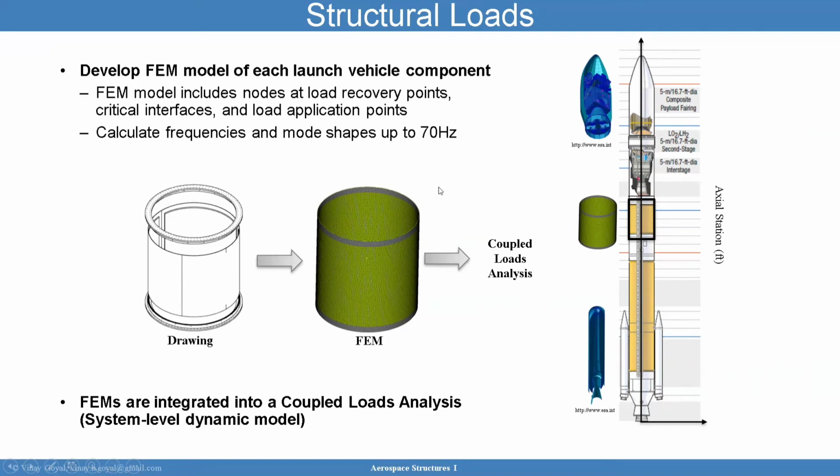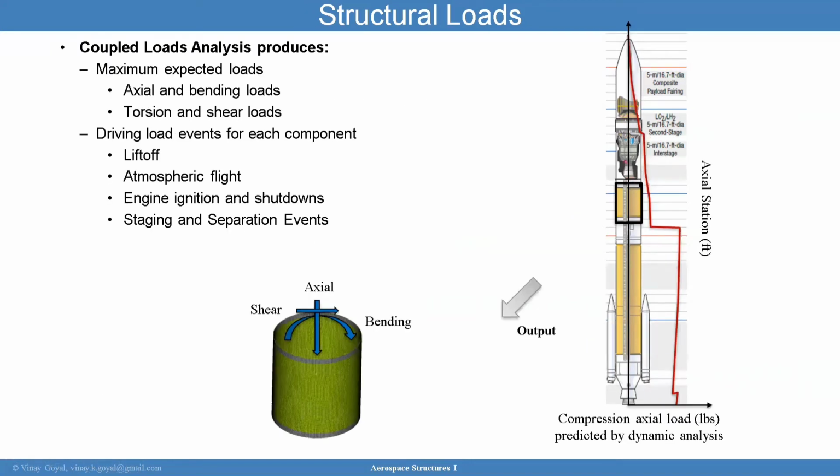And so that model is going to give you important information, driving load events for each of the things we talked about, like liftoff, atmospheric flight, engine ignition and shutdowns, staging and separation events, and so forth.